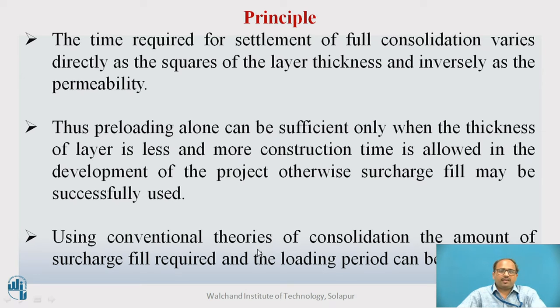So, using conventional theories of consolidation, the amount of surcharge fill required and the loading period can be estimated. By using this consolidation theory, we can calculate the surcharge fill, which means the thickness of the layer, and the loading period. For example, the surcharge loading period means your time period: 1 minute, 2 minutes, 1 hour, 2 hours, because your consolidation is time dependent.